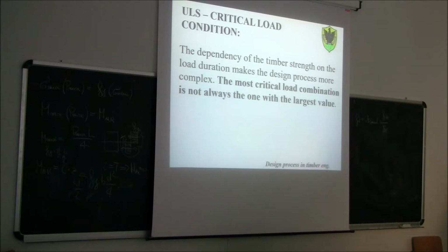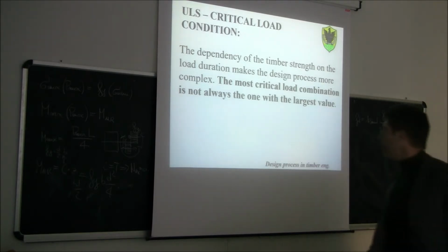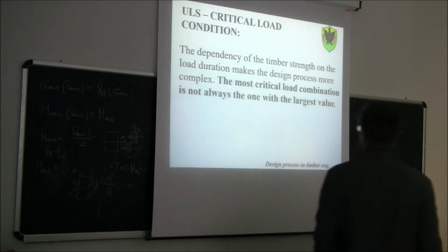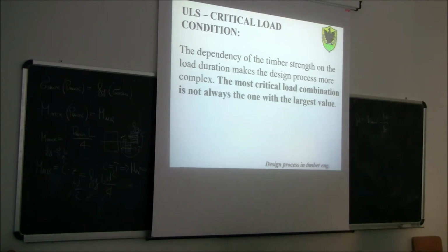Obviously, the dependency of the timber strength on the load duration makes the design process more complex, in the sense that the most critical load condition is not always the load condition with the maximum value. What does it mean?